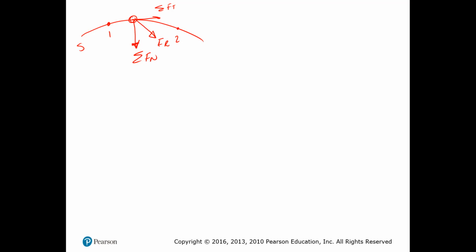What is important about this is why we are using just the equation of the sum of forces in the tangential direction, which equals mass times tangential acceleration. The normal acceleration will make 90 degrees with the displacement, and therefore that component is zero. So that's why we're not focusing on the normal component of these forces. They make a 90-degree angle with your displacement, and therefore, as we defined at the beginning, that will not have any interaction with work, and that's why we don't worry about that.